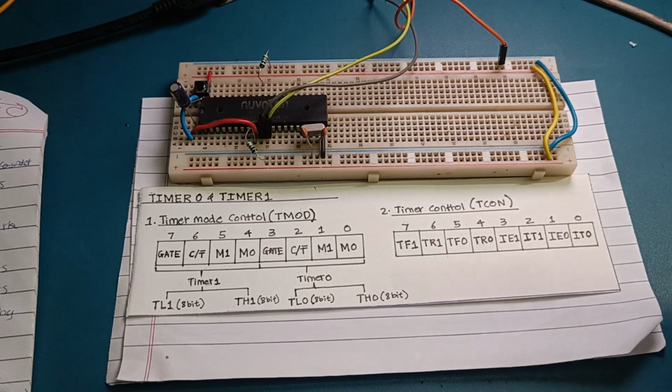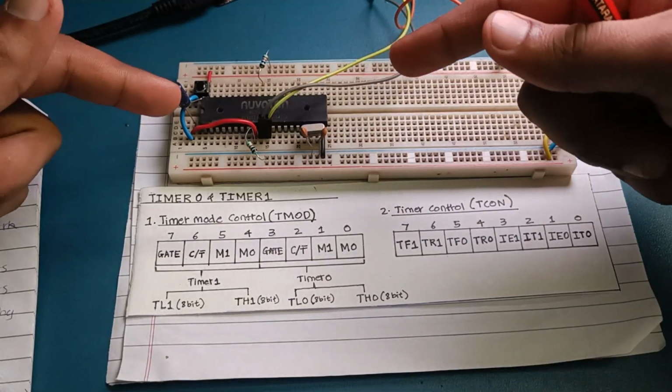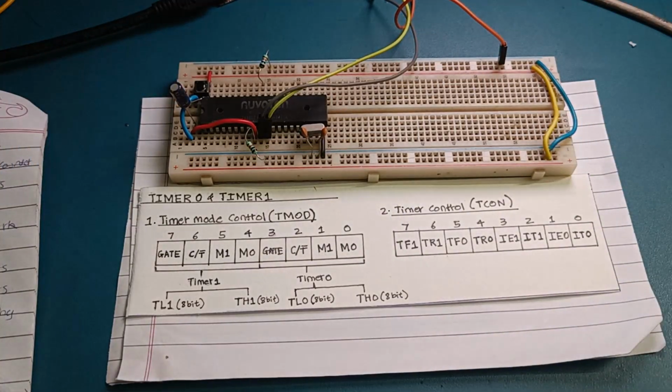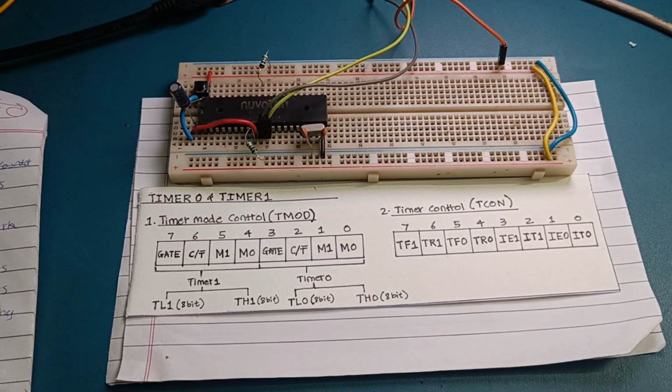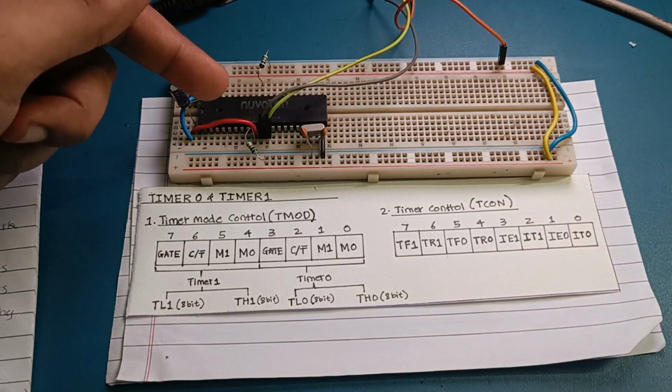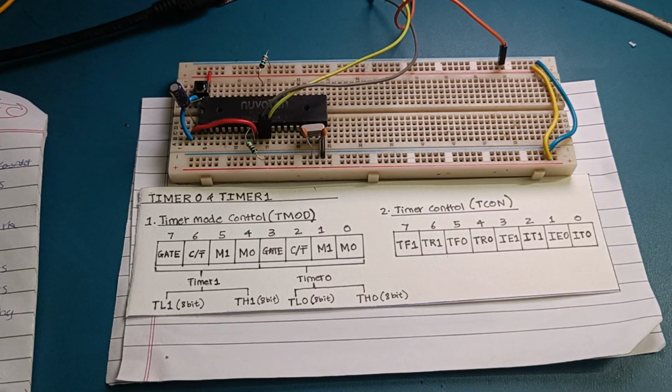So in this video, I'm going to talk about timers in this 8-bit microcontroller by Nuvoton, the W78E052D. My aim is to give you a practical insight on how timers work at register level. There are three timers in this microcontroller: timer 0, timer 1 and timer 2. As it's an 8052 based microcontroller, there is this additional timer 2, which has this amazing feature of capture and up-down counting, which we'll see later.